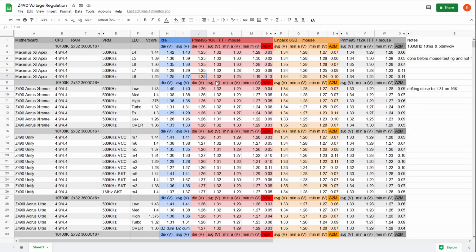The power consumption of a CPU behaves a lot like a resistor at a very, very low time scale, or very small time scale. It's still kind of like a resistor, except a resistor that's changing its resistance very, very quickly, at random, and by very large amounts. And that causes the massive voltage regulation issues because of just how VRMs work. Anyway, we're not going to get into that.